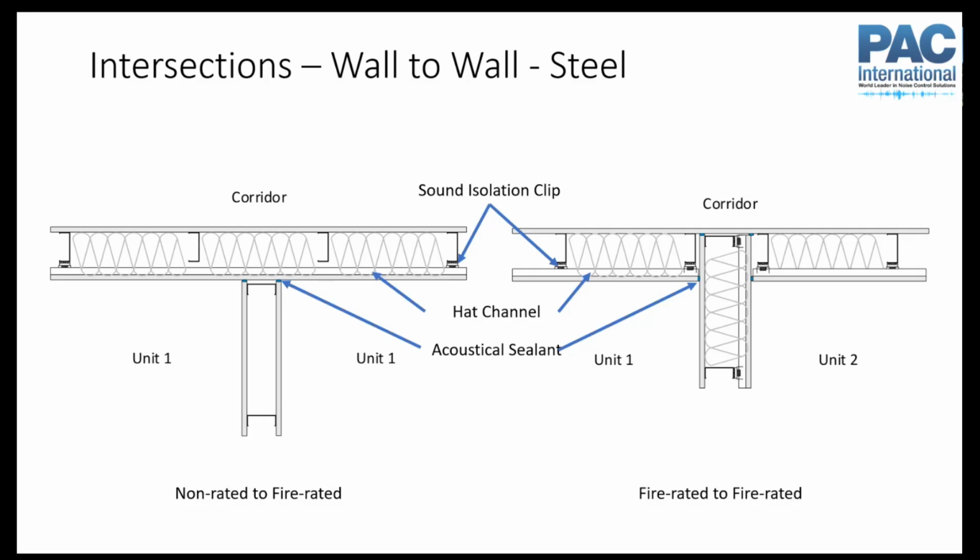or an express clinic or something like that, right? And here's one patient exam room and here's another patient exam room. Well, we definitely want acoustical separation between them, but maybe this is not a fire rated wall, while this is a fire rated wall between this tenant and a separate tenant. So here we have this continuous path. Maybe you want to break the drywall here, but then use fire and acoustical caulk to seal it, almost like a control joint. Treat it that way.